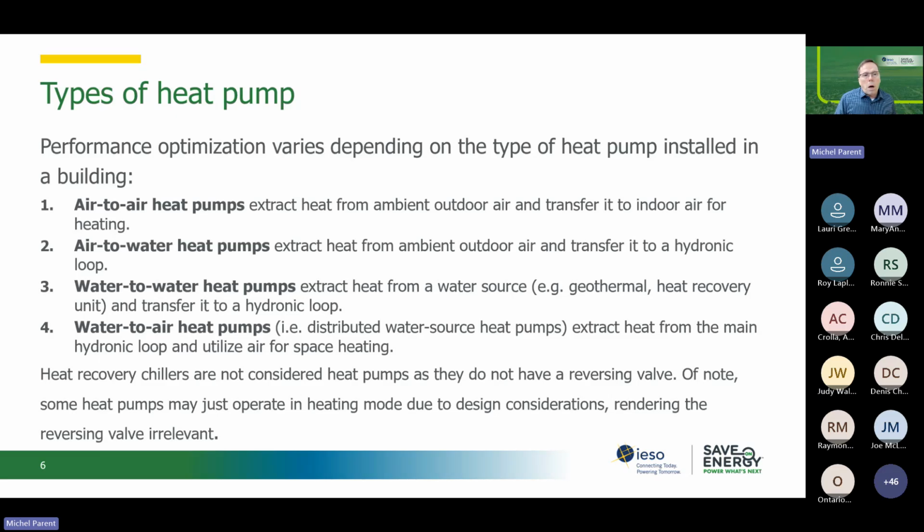When you get to the water-to-water heat pumps, very often, but not always, you don't necessarily have that constraint, because whatever that water source is, where you draw that heat, is not necessarily directly impacted by outdoor air temperature. It can be, but it's not always the case. And again, it will impact how you control that heat pump.